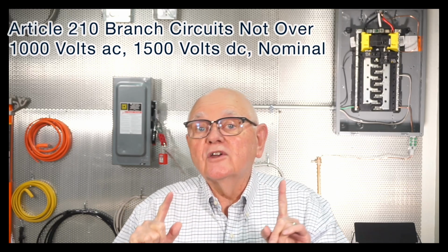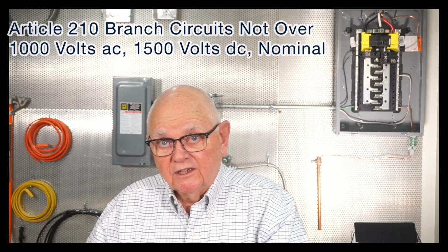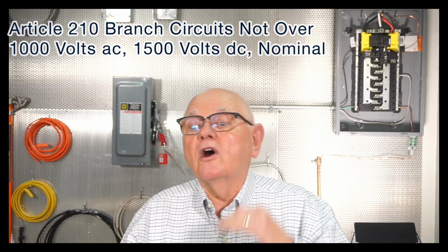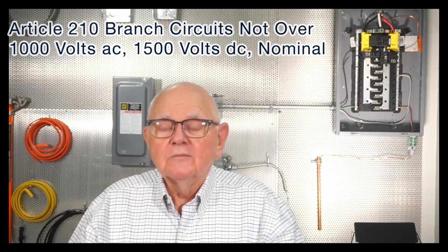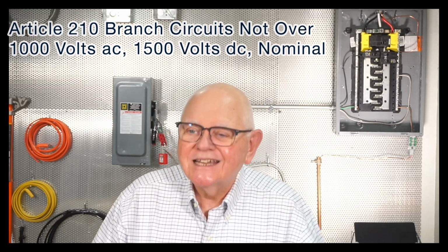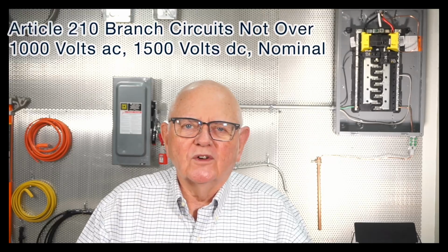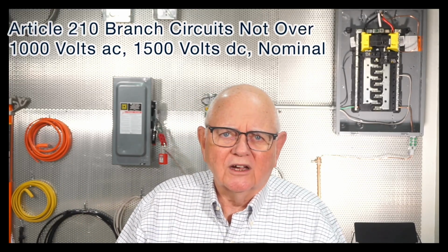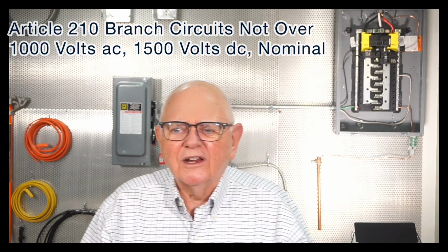It's going to be on Article 210, which is branch circuits not over 1,000 volts AC or 1,500 volts DC. Now, if you need to go over 1,000 volts AC or 1,500 volts DC on a branch circuit, service and feeders, you need to go to Article 235. But we're sticking with Article 210 today for circuits not over 1,000 volts. So most commonly, our 120 circuits is probably what we're talking about. Motor circuits, 480 and so forth.